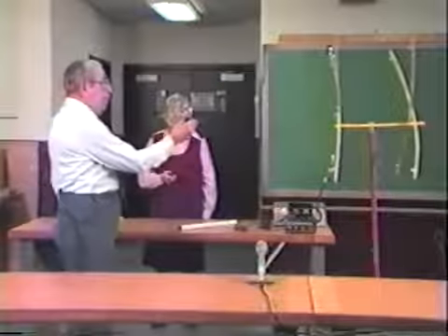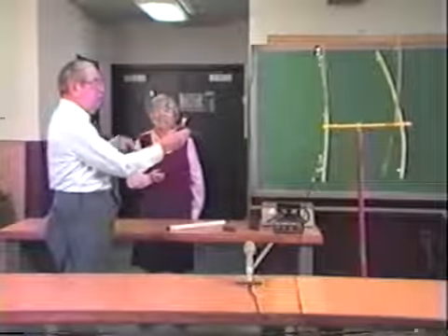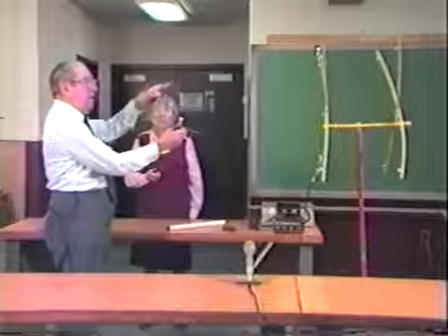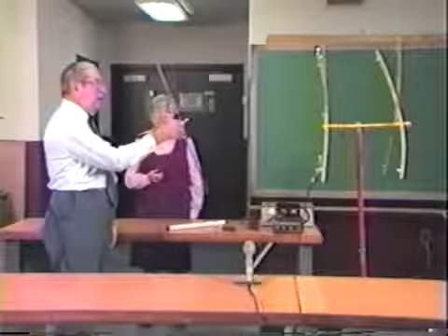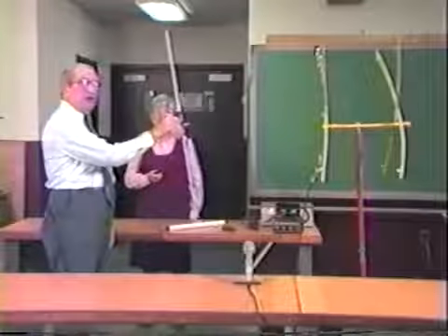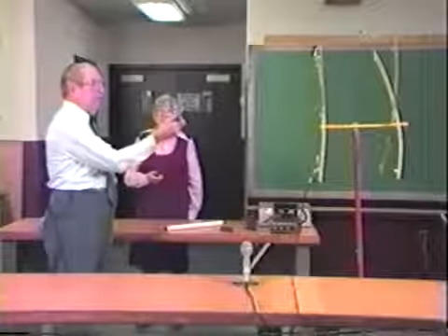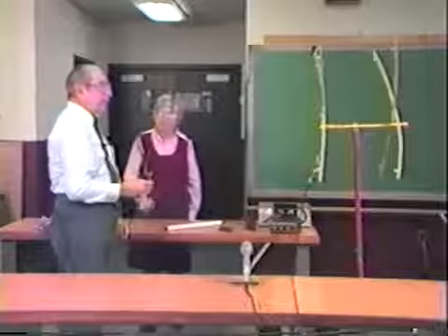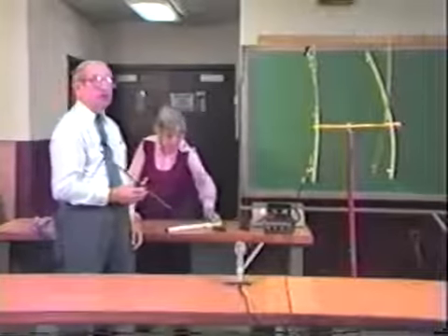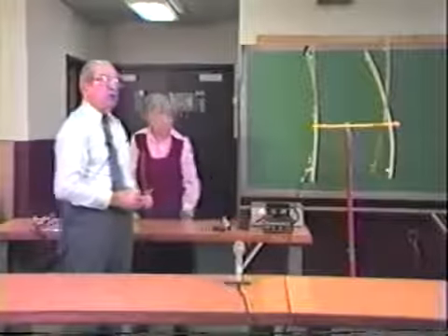And even though the wire is in the form of a square, don't forget it's horizontally polarized because that's where the current loop is. We bring this into the vertical plane, no light. In the horizontal plane, plenty of radiation. So that it's a very effective antenna and a very good antenna. So much for the quad.